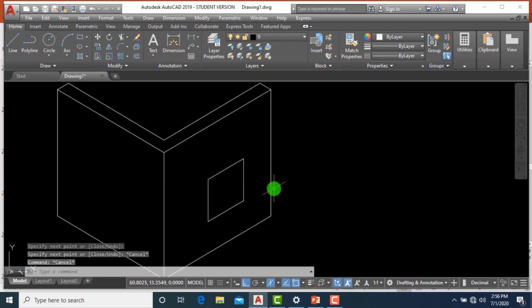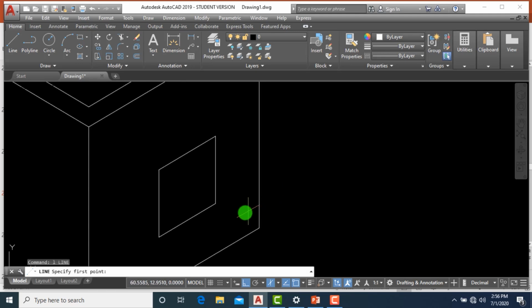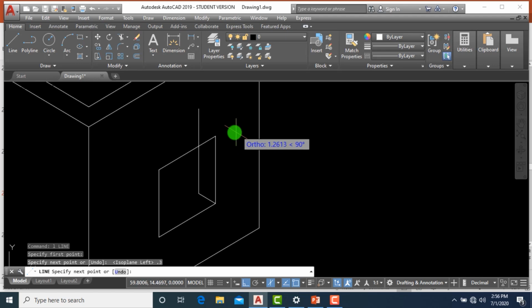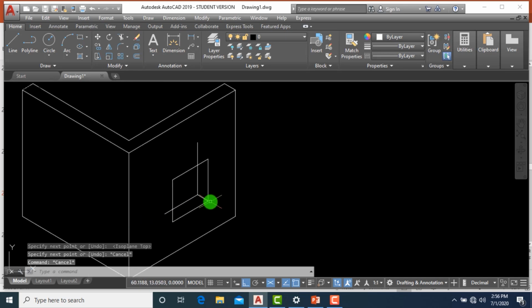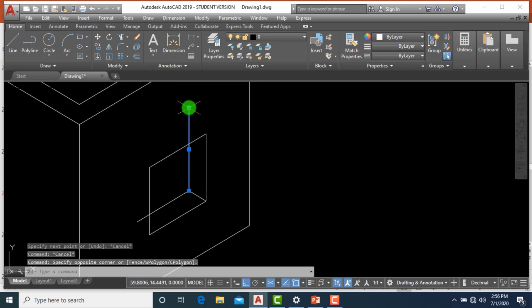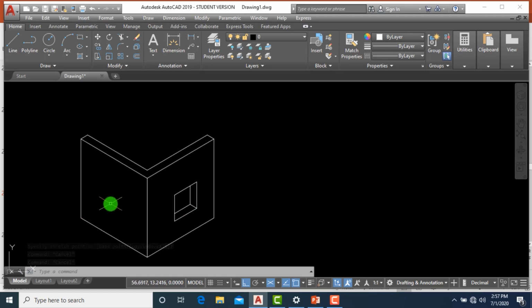So with this there is a face opening over here, and you can create a thickness. Press the F5 key here and 0.3 here, and just pull it down, and here we go, and F5 key, and you can see with the isoplane top. Now in order to reduce it, just bring it down, select it, there's a grip that is visible, put it and get it here. So there's a thickness that can be seen. So this is how a wall can be created in isometric view.